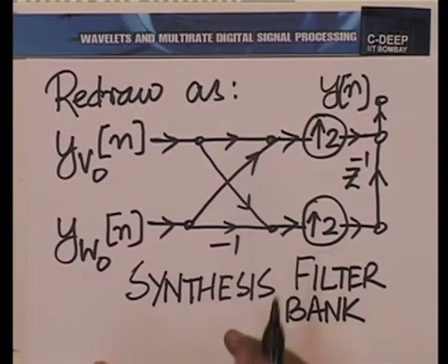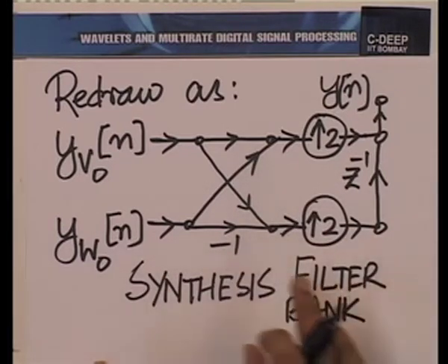I told you somewhere earlier in this course that the Haar multi-resolution analysis and its derivatives, that is the filter bank coming out of the Haar and the other concepts that are illustrated from the Haar, illustrate several different common concepts in multi-resolution analysis very, very lucidly, and this is one example. Here I have a beautiful decomposition of the synthesis filter bank into what is called its polyphase components lying ready for me right here. Now, this word polyphase we will illustrate in greater detail later. What I am trying to say is that the structure that we have drawn right here for the synthesis filter bank actually gives us an efficient way of computing or representing the computation of the synthesis filter bank.